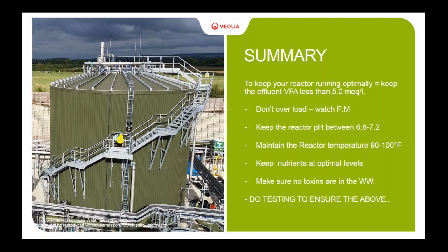We recommend a specific testing routine, but at the same time, if you're measuring your nitrogen every day and it's the same every day, you can start backing that off to once a week or once every 2 weeks, whatever is best for your system. But the effluent VFA is something you should be doing pretty much on a daily basis because it's an instantaneous snapshot of where your system is. And if it's higher than 5, that probably means you have an issue going on that you're going to want to address before it gets out of control.